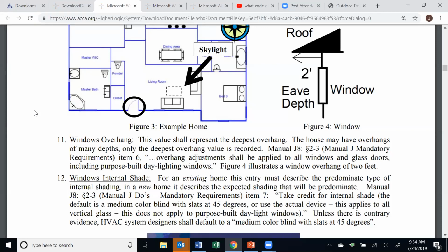But what about window overhang? Basically what this says is, for window overhang, you're using the biggest overhang. Is that correct? Right. This gets back to something that happened with the orientation. So we're talking about window overhang. Which window? The general guidance is, number one, just make sure it was accounted for. If this house has overhangs, let's make sure that they were used. And if you have to pick one, then let's pick one where it's predominant. So if I've got a lot of windows on the side of the house that has overhang, then let's account for that in the calculation.